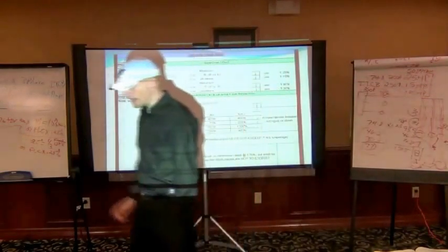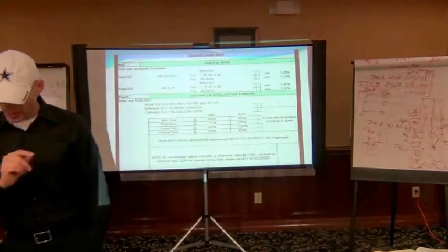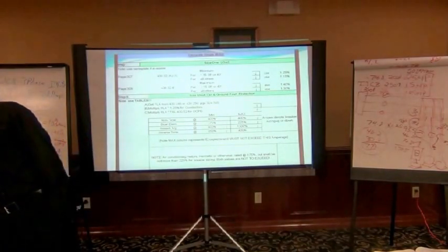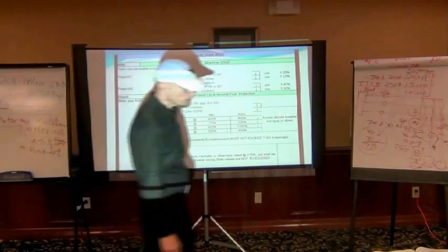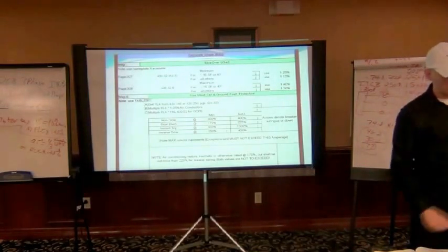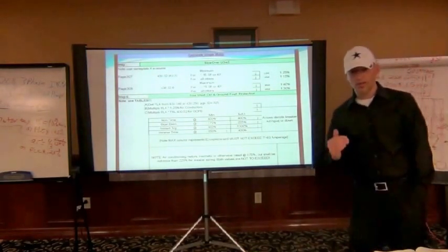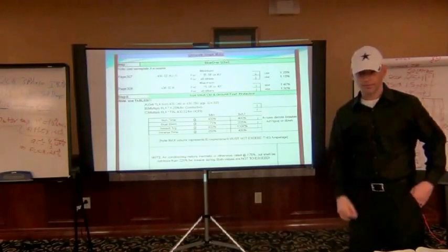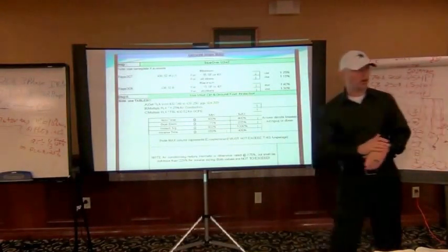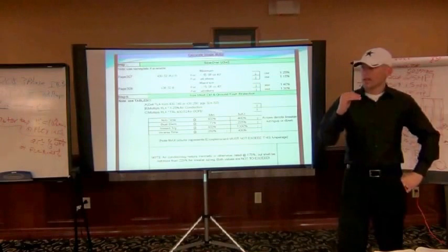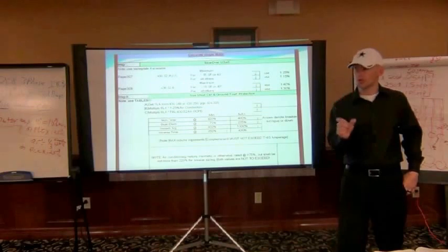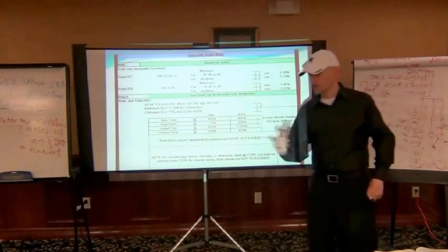And then HVAC, I would just write myself a note on the page that has .52 on it, which is page 323. Right below or above or to the side there, just put HVAC. It's 175, 225. So the same type of protection we're talking about for a standard motor, in Article 440, sizing your protective device for an HVAC motor is going to be 175% or 225%, both round down. That's just a quick note.